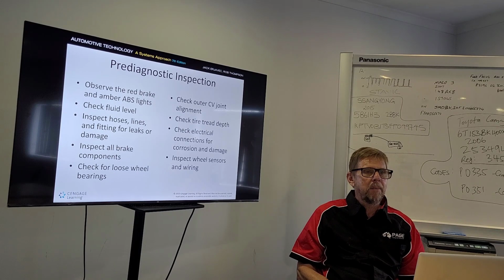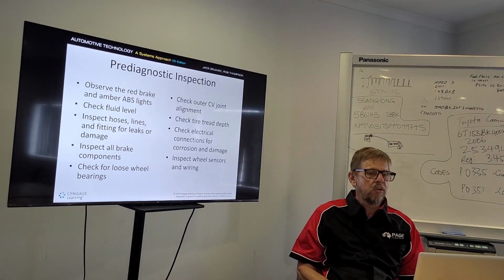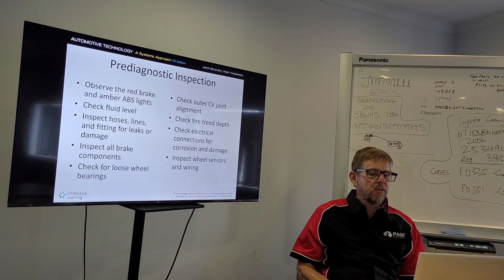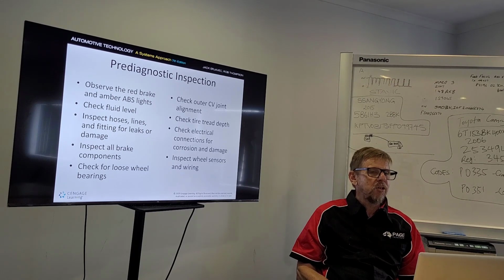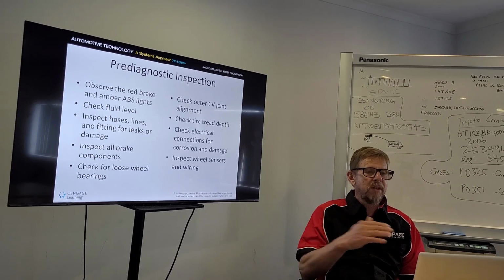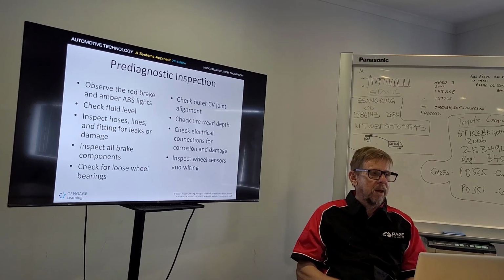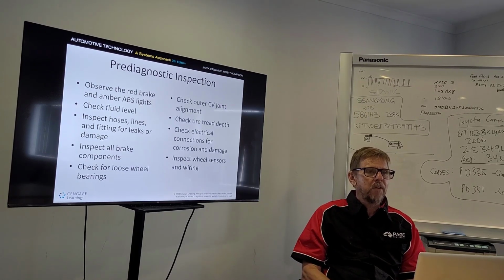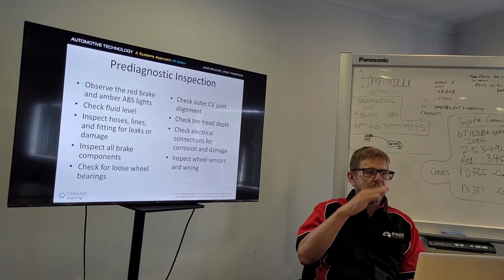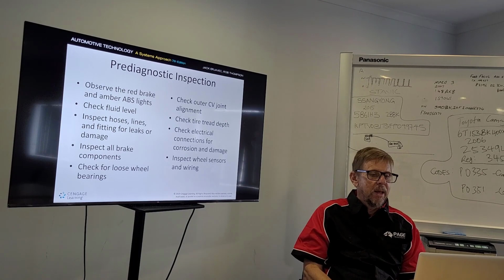It's the same with our brakes, okay? We need to check the condition. Test it for moisture. Could have a lot of moisture in it. Inspect the hoses, the lines, the fittings for leaks or damage, okay? Sometimes people have been bush bashing their vehicles, and something's stretched and they've got a crack in their hoses or whatever, who knows? Even that last video we saw with Jeff, where he's showing you where the vehicle goes up and down and how you break that wire over time, check things for that.